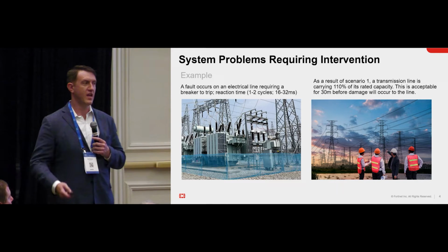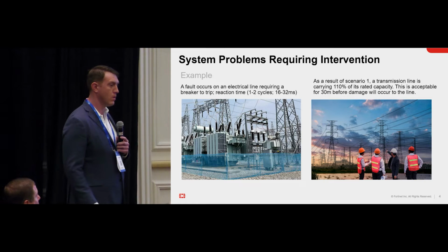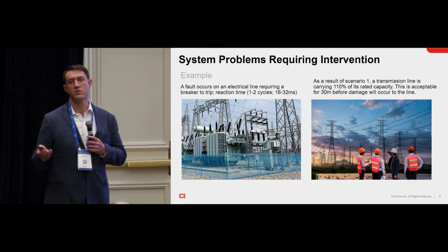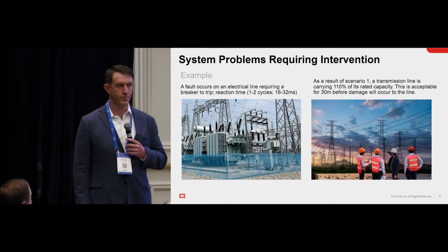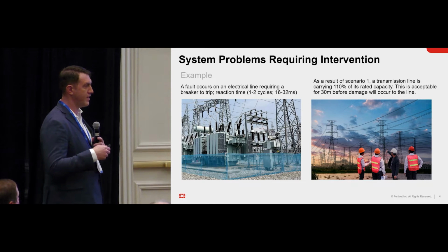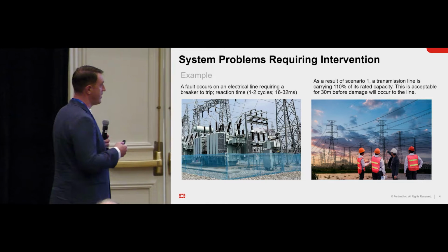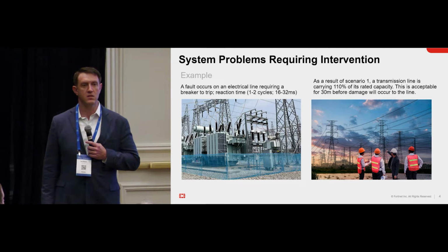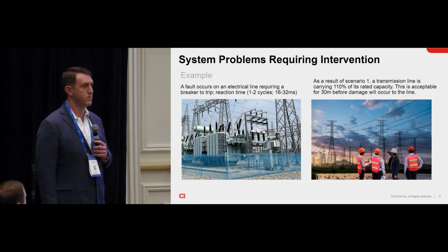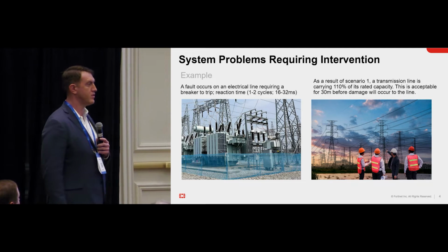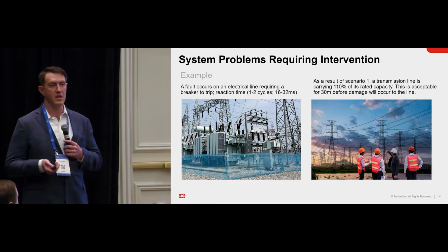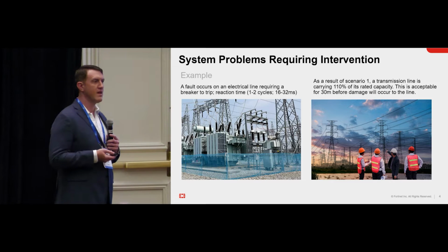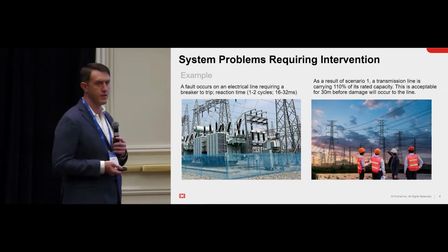When you interconnect with a large transmission owner, you are told if you have a fault within your system, you have 125 milliseconds to trip, right? And you have to backwards plan that. And what you usually end up with is you have 1 or 2 cycles, which in North America is 16 or 32 milliseconds, to be able to trip, right? Including breaker operation. That is obviously well beyond the ability of a human to make a decision, right? So we have engineered systems for that, okay?